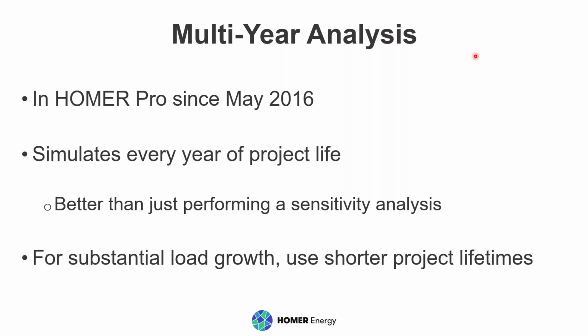One caveat I want to mention: one of the most important things that can change is load growth, or the load in general. If it's changing in any substantial way, you probably want to break the full project life into shorter periods. That is how you could model going back in and enhancing the system. It used to be that grant-funded projects would overbuild in the beginning so they didn't have to go back later, which is difficult for a grant-funded project. But it's also not very cost-effective to overbuild initially.